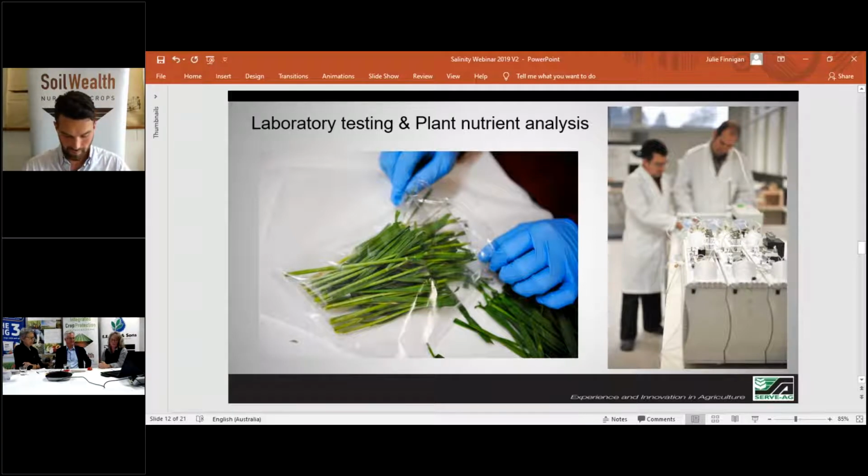The other really important thing is that we need to calibrate these quite regularly and clean them properly, or else they will give really poor results. But if they are managed well, they will last a long time. Even still, I'd strongly suggest putting some samples through the lab fairly regularly, just to make sure what you are testing is correct.